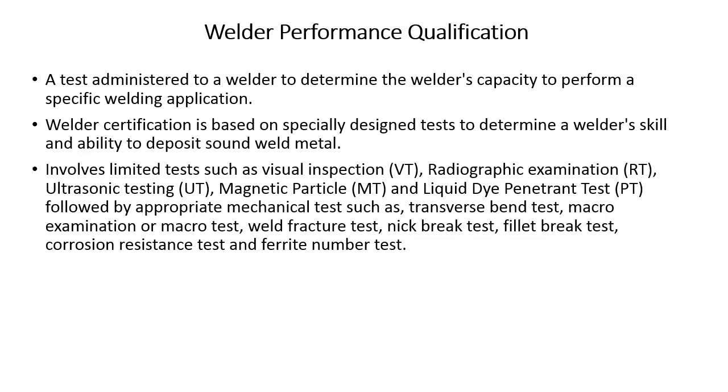But it could involve just VT, radiography, mechanical tests. Just depends on what needs to be done to satisfy the specification and codes that you're working to.